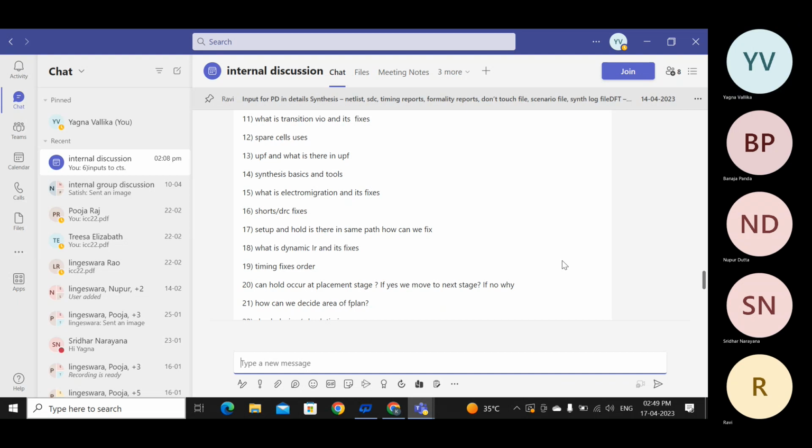spare cells are in addition to that. By design, I have some functional failures coming. See, with ECOable cells, there are going to be functional failures in this part because it's not verified properly. Okay, so I have some issues in this. Then they would add some dummy cells. The point about ECO and spare cells are different. In the spare cells, you would not connect the input and output, you will just leave them hanging.